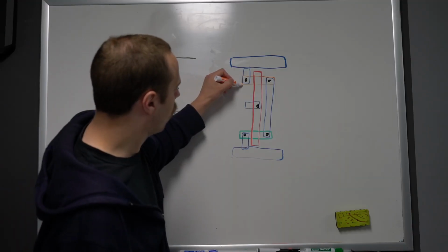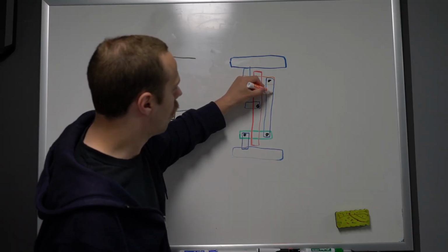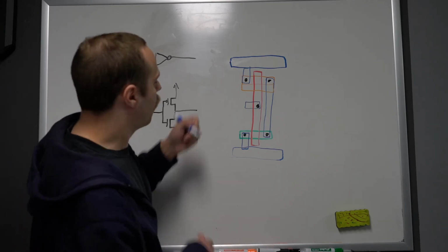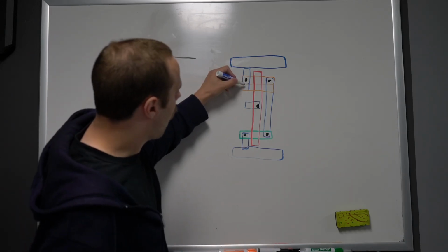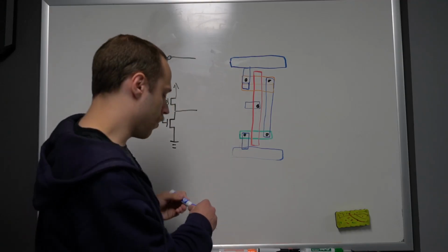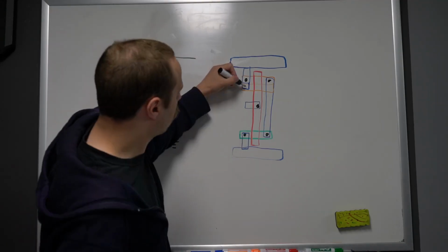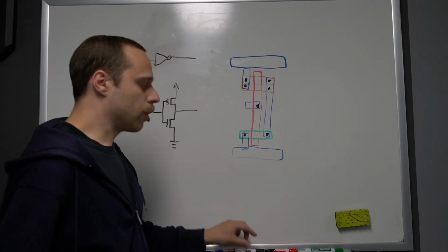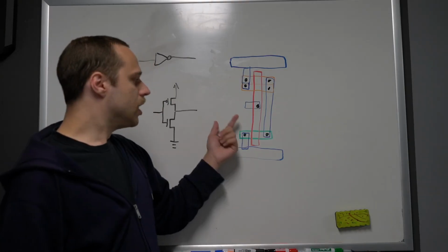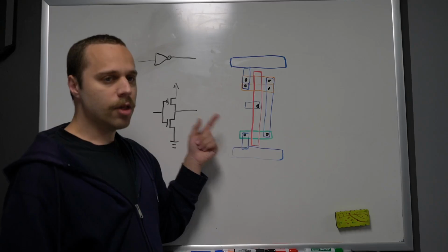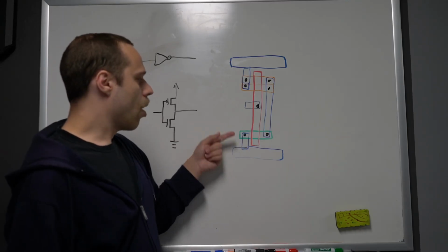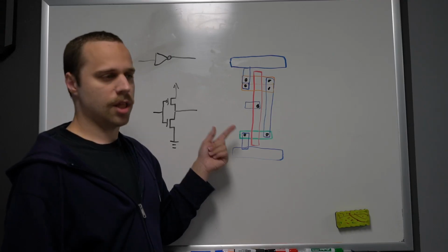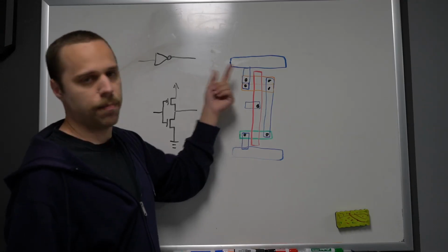And so typically what we would actually see is, in a more realistic gate, we would have a PFET that's a little bit taller, and we're going to add that metal strap a little bit wider, and let's just say, for the sake of discussion, we've got 2 contacts. And so this gives us a very useful clue as reverse engineers. We don't need to be able to see the doping. If we see a complementary pair where one side is about half the size of the other, that's a pretty good indication that the small one is the NFET and the big one is the PFET.